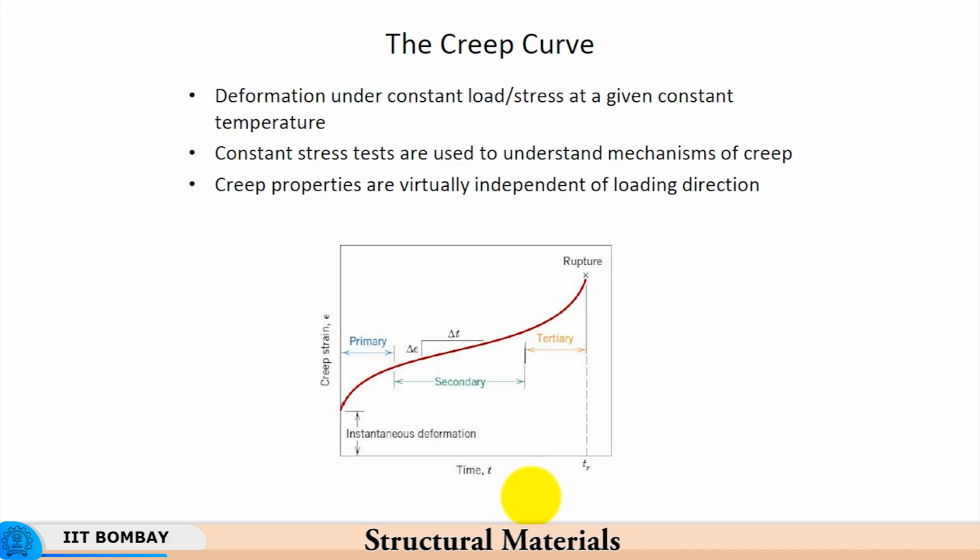That is because creep as a phenomenon is significantly influenced by diffusion, and diffusion is a time, temperature, activation energy controlled phenomenon. So, when we study creep, we look at the creep strain and relate it with time to find out whether the strain rate remains constant, or whether it is increasing, because when the strain rate increases, the rate of depletion of cross section increases, as this is all plastic, permanent deformation. If the strain rate increases very rapidly, there is a rapid depletion of cross section, and therefore the stress correspondingly increases, and the material being soft as well as permitting diffusion of atoms will result in a very rapid reduction in the cross sectional area. That is what is indicated over the curve here.